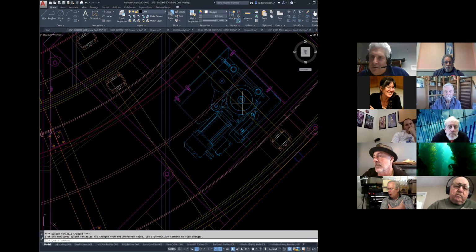But the trick of this that has proven to work really well is that both this motor and this friction wheel are free to pivot on this point, so that as our circle, which as well as we can fabricate it is never perfectly circular, moves in and out a little bit and waves a little, our friction machine can rotate and move with it, so that we always maintain good friction onto the ring with our driver, even if it's wavering in and out.